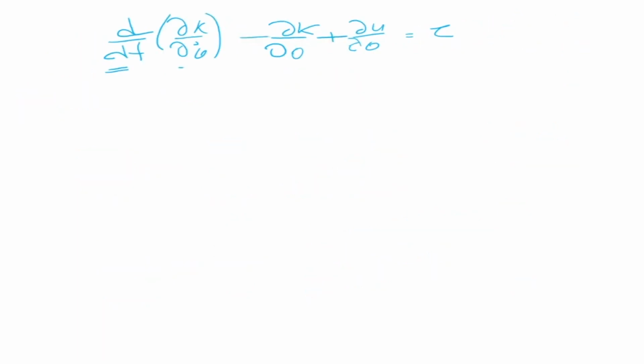So if you do that, what will end up here is tau 1 is equal to, I'll write it in matrix form, okay, let me write it this way only, is equal to (m1 L1 squared plus IZZ1 plus IZZ2 plus m2 d2 squared) into theta 1 double dot.